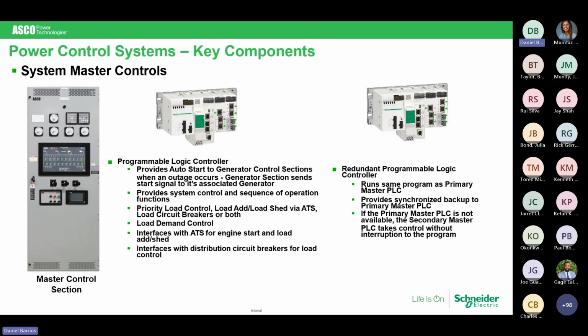We tell you, please give me 2 Ethernet cables, give me these shielded cables for each of the bias runs to the governor and to the voltage regulator, but I also need 24 number 12 wires pulled between. Why? Because it is coming into these annunciation panels. It is making sure that shutdowns and pre-alarms to not damage your generator set are active and they are directly into the system.